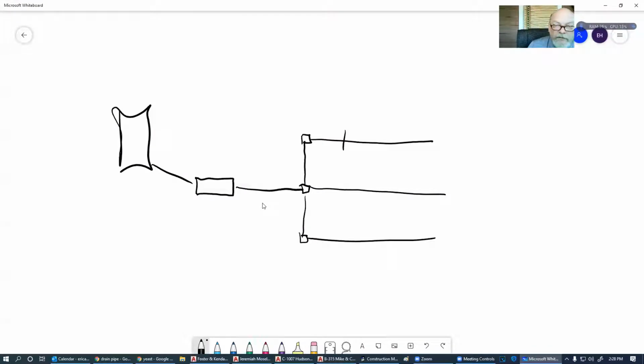We're going to cut through here, and we have our drain field, and we're going to put this in. Where do the holes go, up or down? They go down. Even if we were to use these for the same drainage system that we're talking about on the footings, they go down. We want to catch the water first and get it to the lowest point. We don't want it to fill up to this point before it can go in. So definitely make sure that the drain holes go down if you use that type.